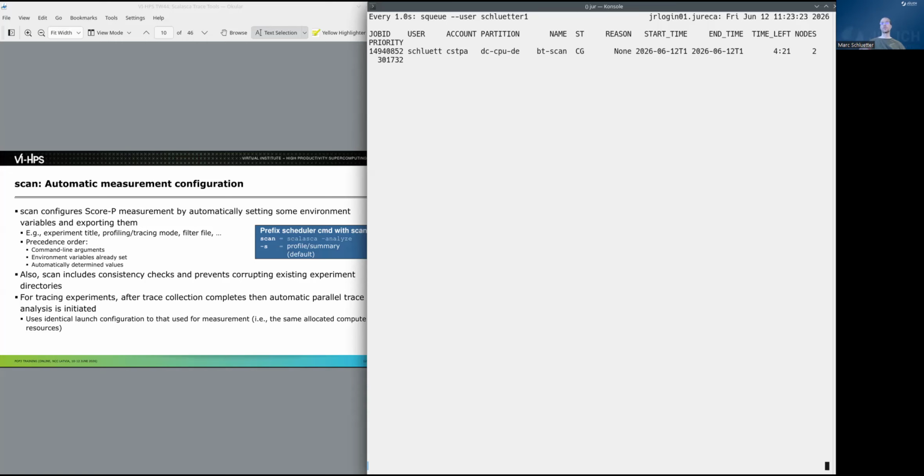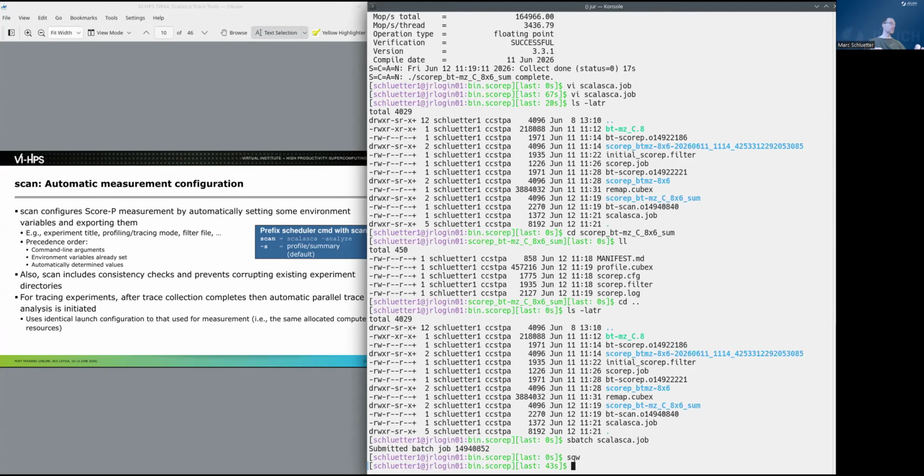So in general terms, once you see warnings of buffer flushes in your measurement, you should generally rerun your measurement with a higher set of total memory if possible, or stronger filtering to reduce the memory requirements.